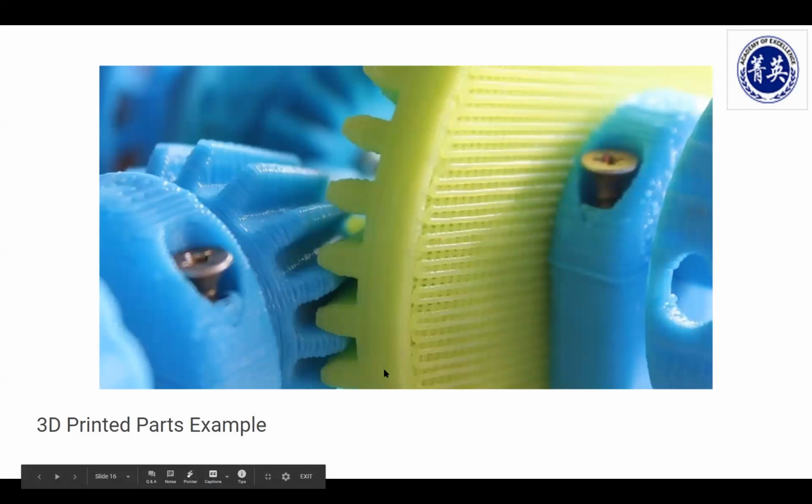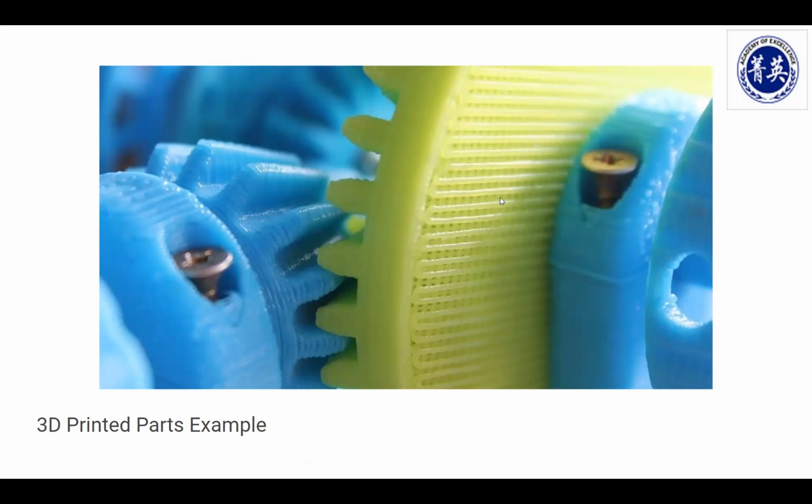Now, given the nature of a 3D print, it is not perfect, right? This is generally what a 3D printed part looks like, since it is built in layers. You can see the light green part, this is the base of the print, and then it builds each layer at a time to make up the 3D object. So the quality of the 3D printed part is sometimes in question. Depending on the material, it might not be very strong. And also the mating surfaces could be really rough.